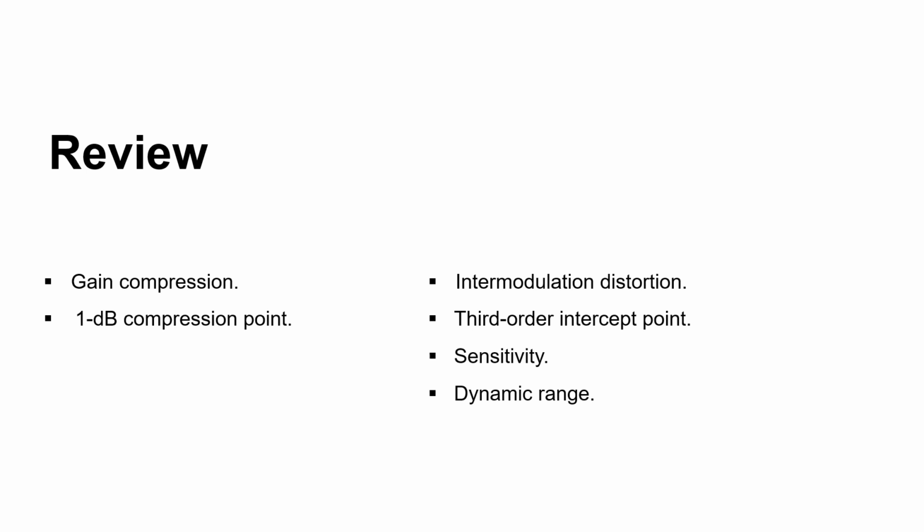We do not want intermodulation distortion. We do not want our amplifier to operate at a saturation level. We want them to operate at a high gain level where they can actually give us a gain value, and that is the definition of maximum power level and minimum power level of our receivers. And thank you very much for listening.